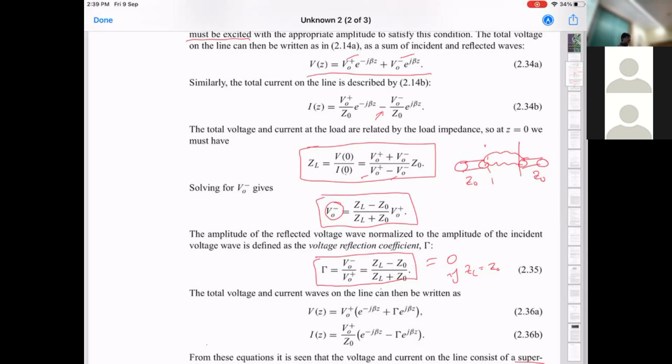And here is a practical piece of information: it is extremely hard to make such connections. There's nothing like a perfect connection at all, where you have absolutely zero reflection. So it ultimately boils down to knowing how much of a gamma is tolerable. Right? And this again depends on whether your goal is to deliver power to some device, or whether your goal is to control some impedance very precisely. So then these tolerances become very, very different.